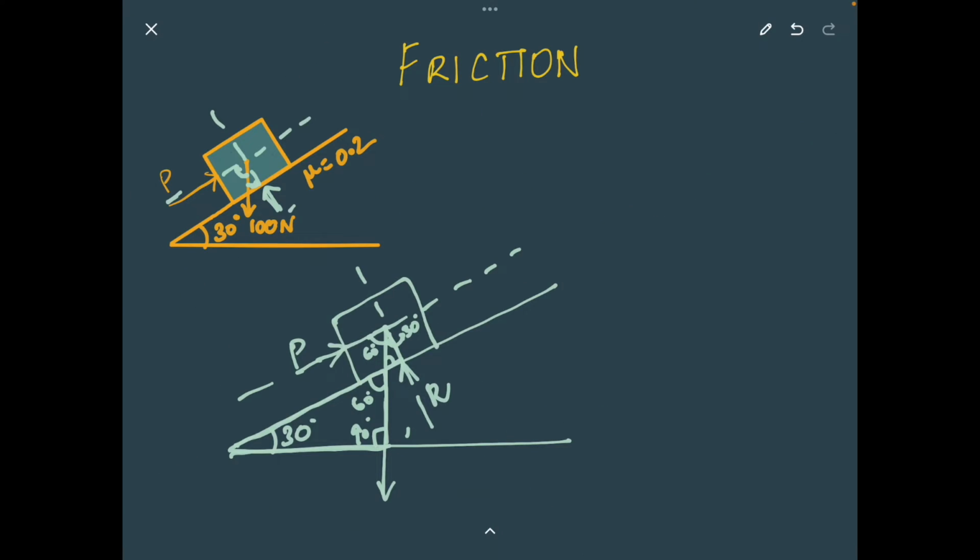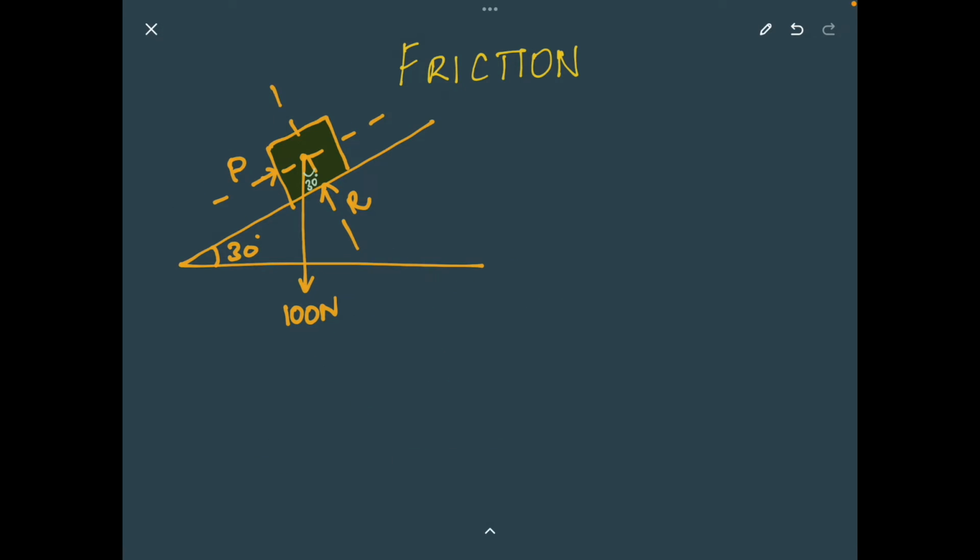So now that we have the angles 60 and 30 degrees, we can take either one of these and resolve this self-weight force into the horizontal and vertical components. For convenience, we have the inclination angle as 30 degrees. So let us take 30 degrees as the angle of inclination of this inclined self-weight and resolve that into its horizontal and vertical forces. Now I have redrawn the system.